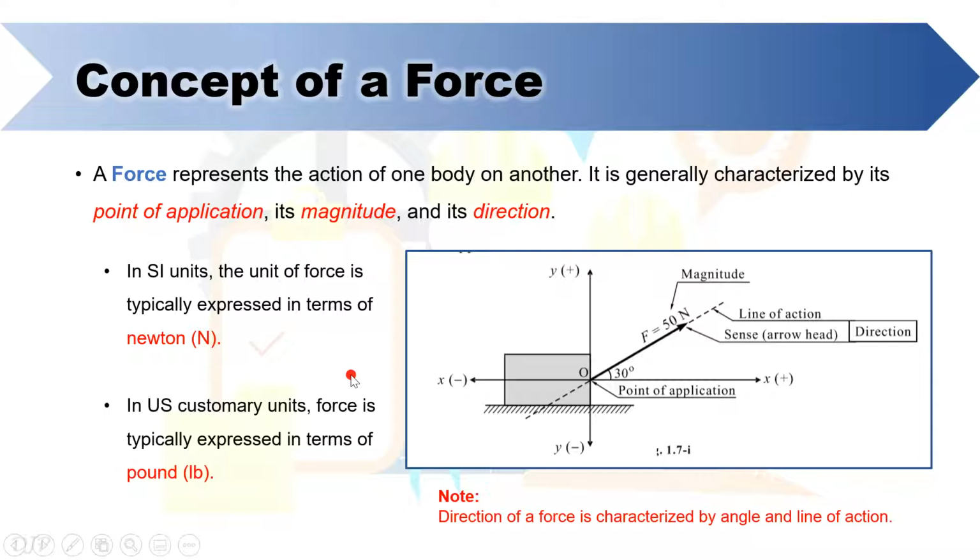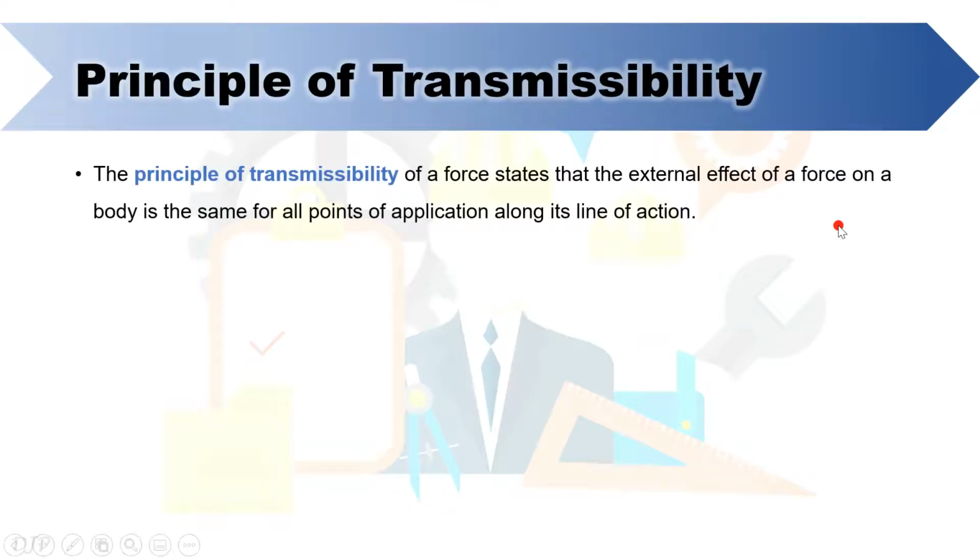This time, let's discuss a very important principle that you can utilize when solving problems involving several forces, which is the principle of transmissibility. It states that the external effect of a force on a body is the same for all points of application along its line of action. This means that when analyzing mechanics problems, you may draw the forces to be not in contact with the point of application as long as it is still acting on the same line of action.